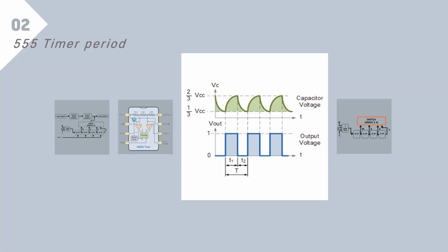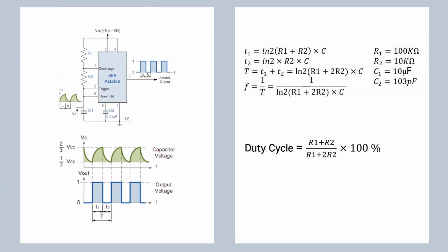This is the cycle control of the NE555 element. It is determined by the frequency, period, on time, off time, and the values of R1, R2, and C attached to the outside of the 555 IC. Through the resistors and capacitors we used, we calculated and found that 4.8 seconds are produced per cycle.